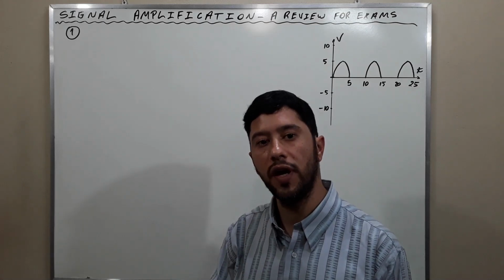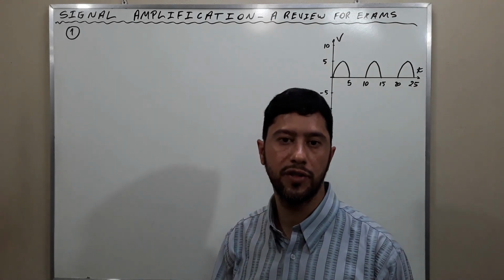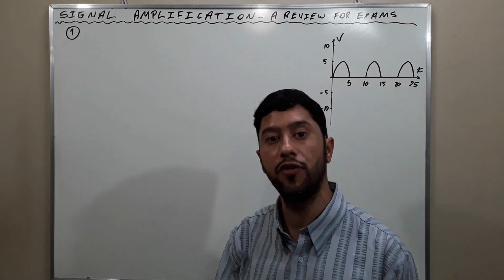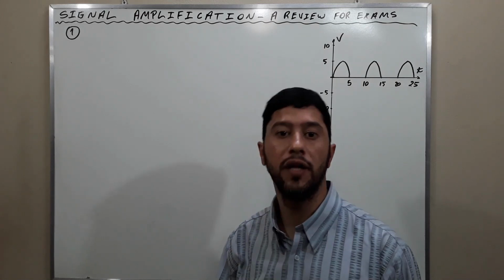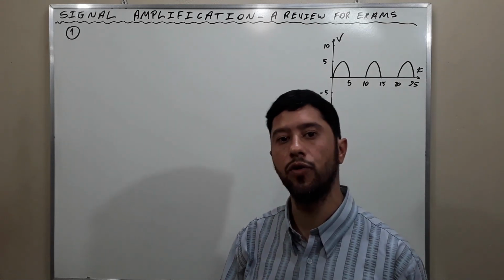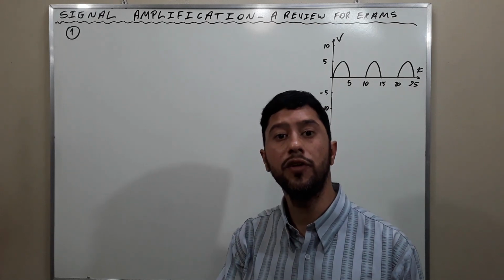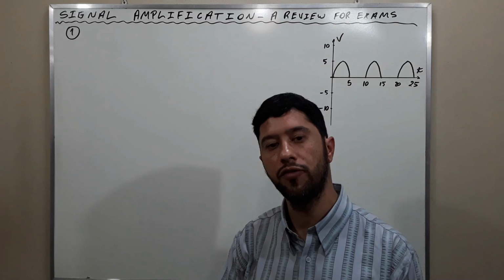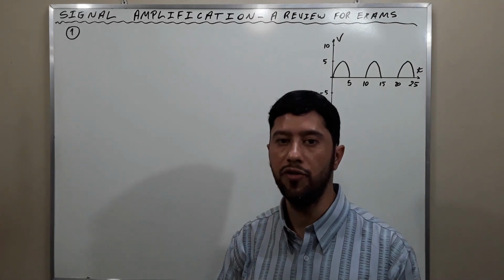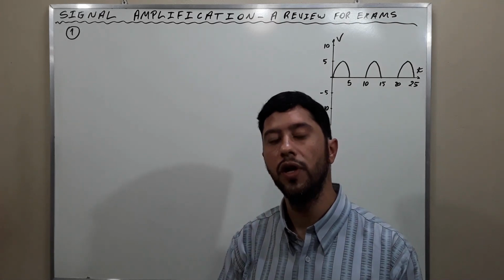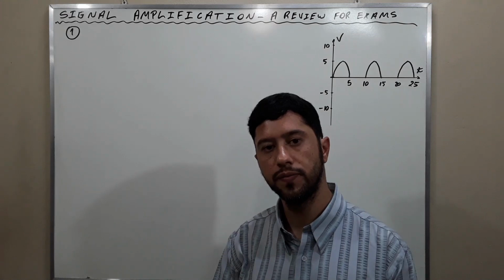The need for amplification arises because sensors provide signals that are said to be weak, in the millivolts or even microvolts range, and possessing little energy. Such signals are too small for reliable processing, which is made much easier if the signal magnitude is increased.